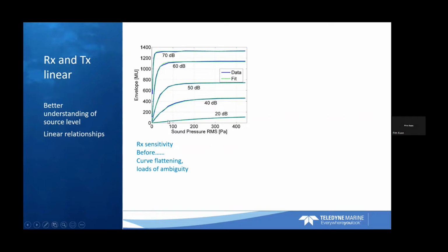If we look at this graph here, on the left is the intensity of your backscatter value, just registered as a machine number, right? If we look at any value at a given range and a given gain value, you could relate that to a sound pressure, but very quickly the curve flattens out. So very quickly you'd be receiving data that sits in this curve, and you can't really make anything of it, right? It's not linear, and that was really the problem with our 7K systems.